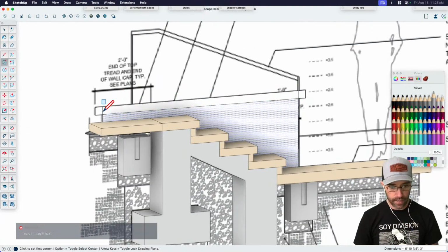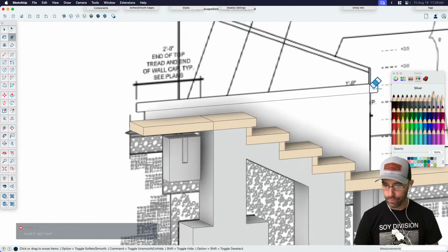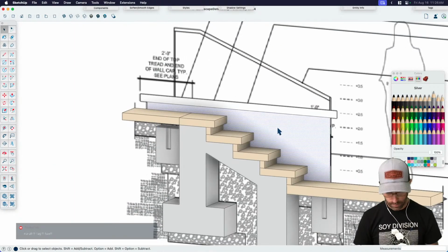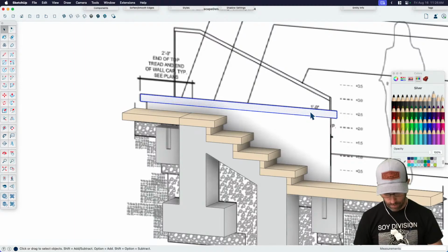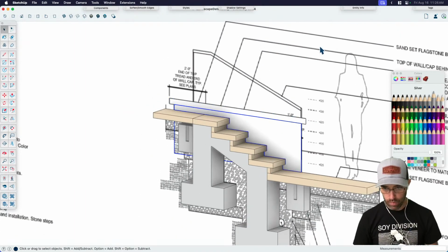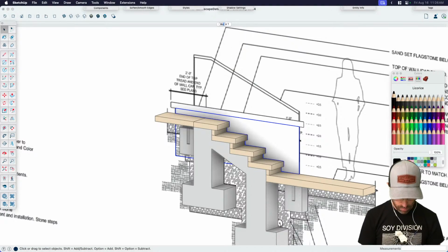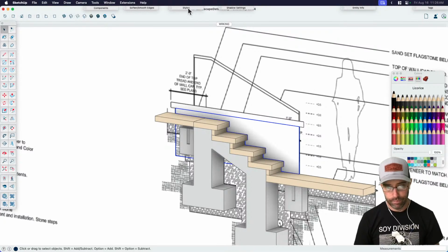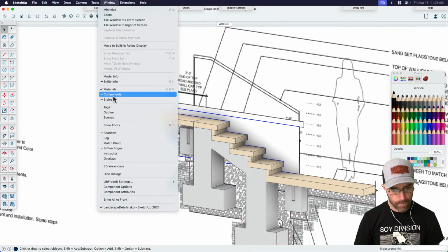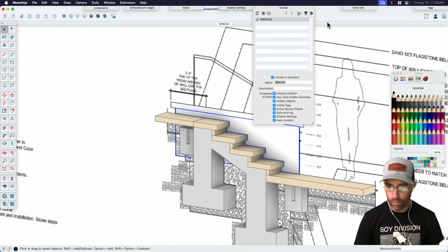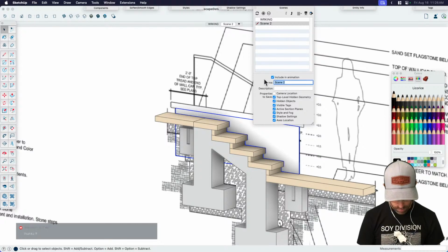So that way I don't have to draw so many times if I don't want to. Yes. And for a total beginner, to start that operation, you select the tool, you click once and release the mouse button to start, and then that's where you just type in the dimension. Like Eric said, you don't click anywhere. You just click once to start the operation in the direction that you want the line to go, for instance, then type the dimension, then hit enter, and then it'll go to that exact dimension.